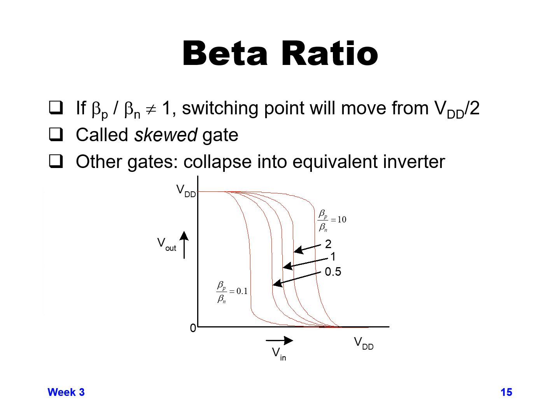So in the previous slide, I had mentioned that if your NMOS and PMOS transistors are really well balanced, such that your beta P and beta N are equal to each other, then you're going to look like in the curves below, the one that is labeled with a 1, beta P to beta N of 1.